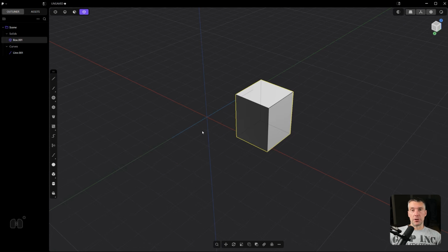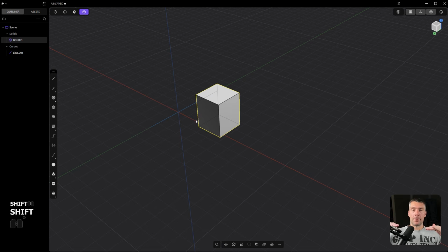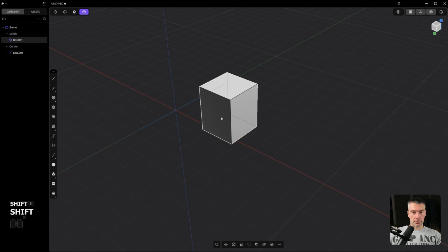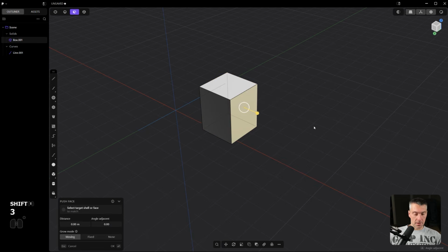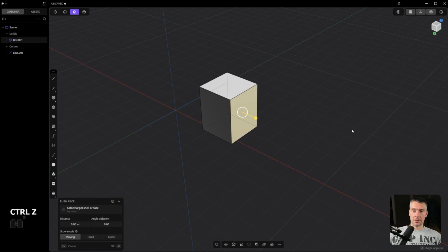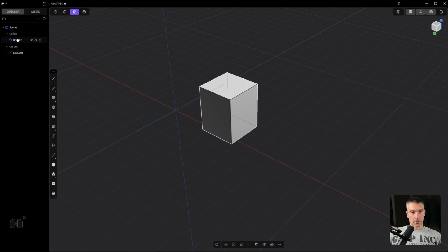Next we have sheets, which are basically like planes, so they're not thick, it's just a very thin layer of mesh, right? It could also be non-manifold solid. So if I go to 3, select this face and press Shift X to delete it, right? Then you will see my box will shift, if I confirm this, to sheets. You see that? And if I go back with Alt Z, just like in Blender, my face is gonna be recovered, you see it's back to solid.